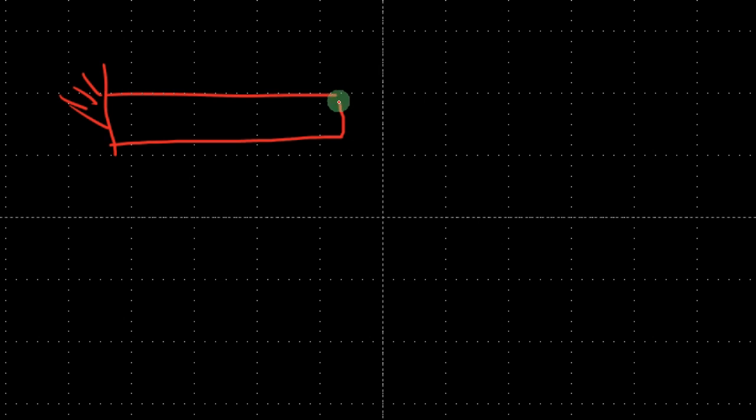If I have a piezoelectric, so we're going to call the red the non-active material. And if we have that big non-active material, and we have a little piezo, very skinny on there, so we can basically neglect its contribution toward the area moment of inertia.